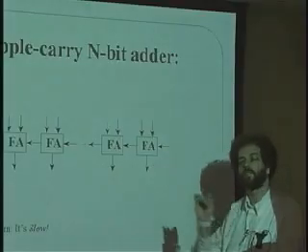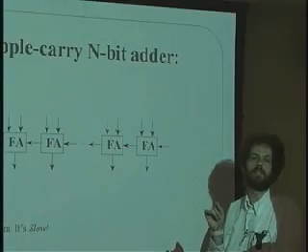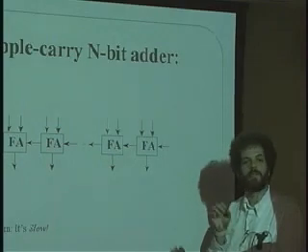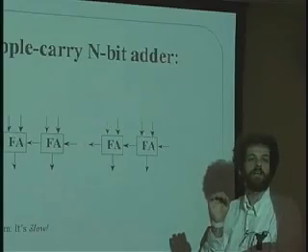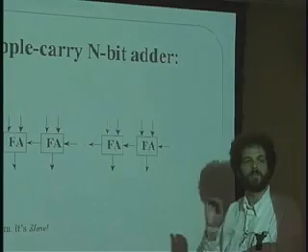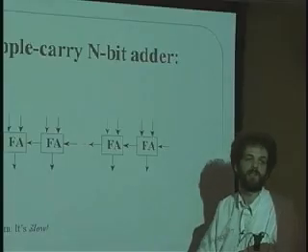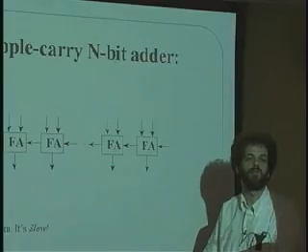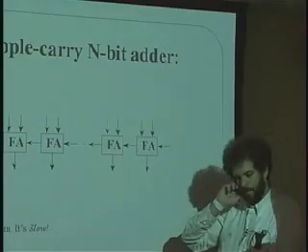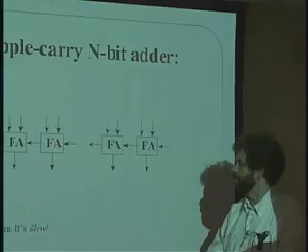Okay, and in general, the rule with a simple adder like this is if the carry out agrees with the sign bit, then no overflow has happened. So in the case of a positive number, the sign bit is 0, and then you expect the carry out to be 0 also. However, if the sign bit is 1, meaning the number is negative, and you add 2 numbers together, and you do not get a carry out of 1, then something's wrong. It means you've overflowed going negative. Okay. So anyway, that's a general issue that we're going to have to figure out how to deal with: overflow in these summations in the ALU.